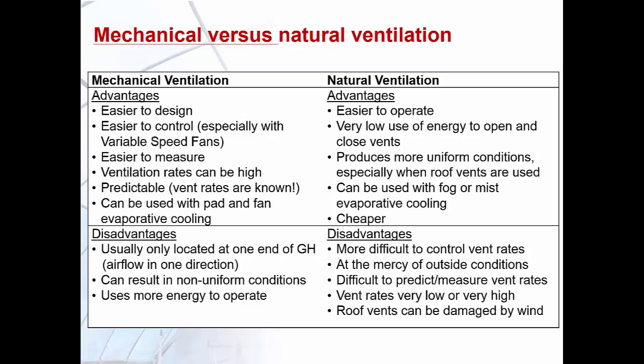Some disadvantages of mechanical ventilation are that the fans are usually located at one end of the greenhouse, so the airflow is in one direction. These systems can lead to non-uniform conditions in the greenhouse space, and mechanical ventilation uses more energy to operate.